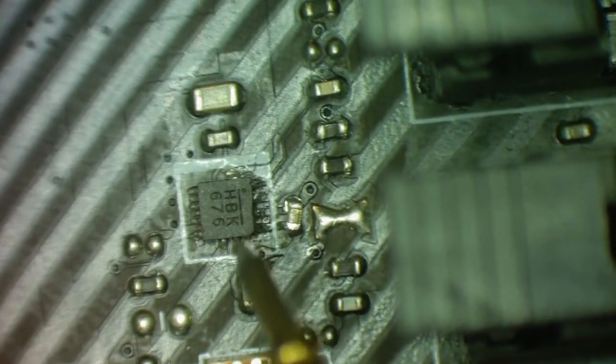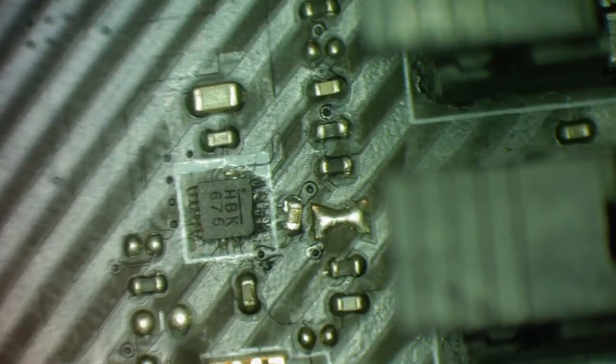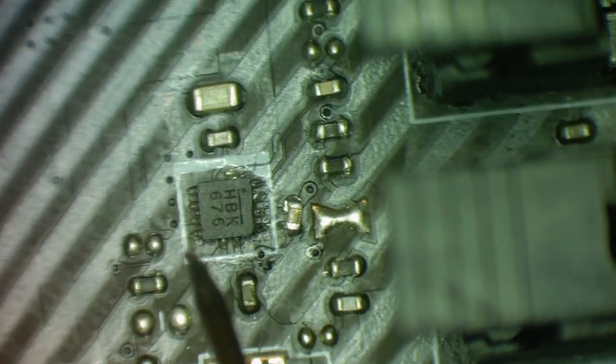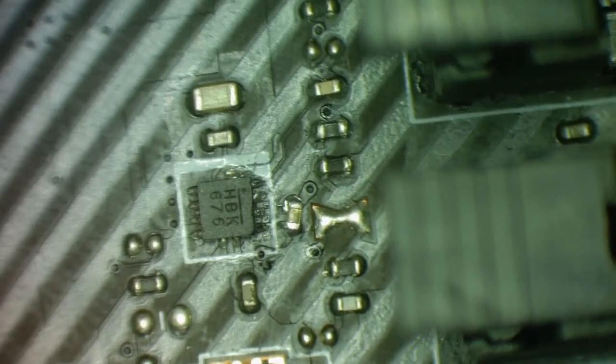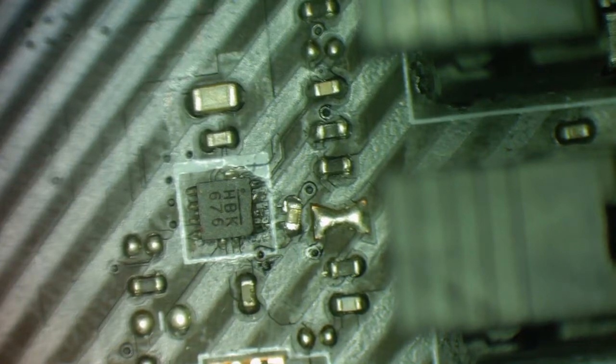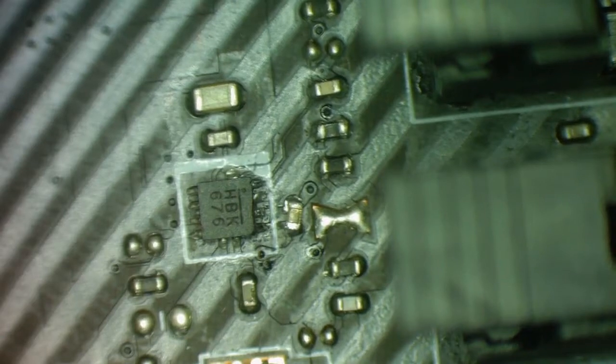So this marking, when you see like this line HBK and some numbers, that's not actually a part number. And the reason I know this is because when I first saw one, I couldn't find a data sheet, and somebody on the internet told me how to do it. These like 3 letters, 3 numbers like this. This is a company called MPS, I think it's Monolithic Power Systems, who make voltage regulators and have these funny SMD codes on them, yeah. And basically the first 2 letters HB will be the product ID. That'll refer to the part number, yeah. And the rest of it, the K676, is like a date code or a batch code.